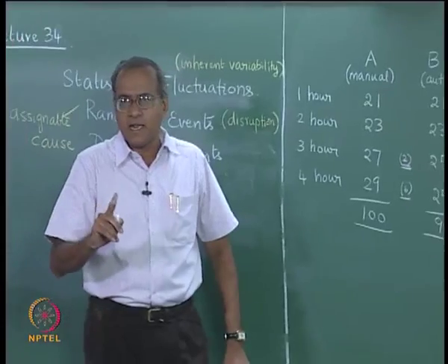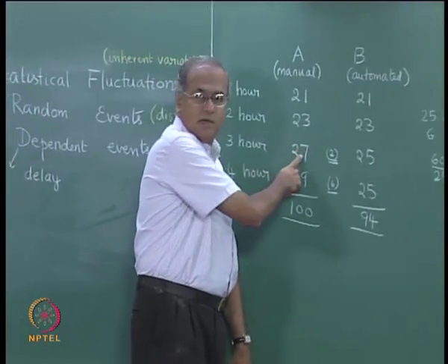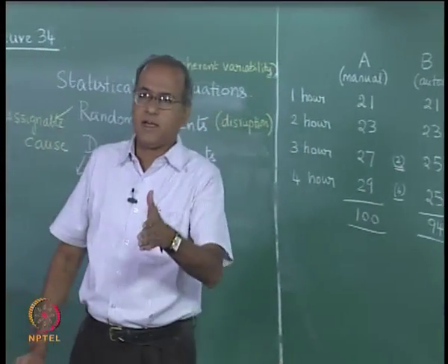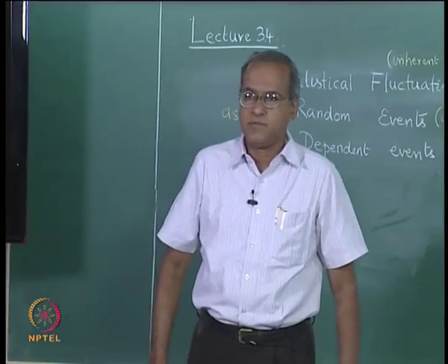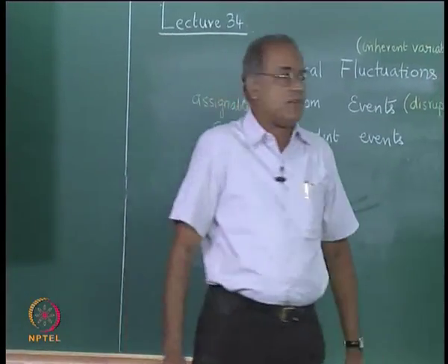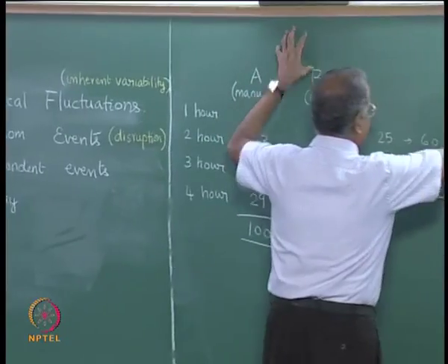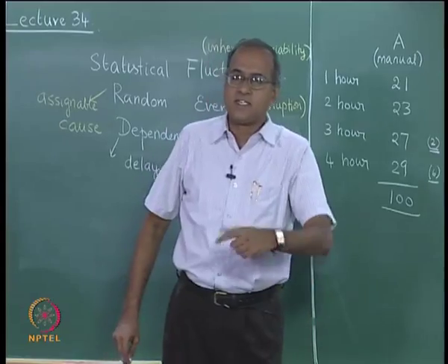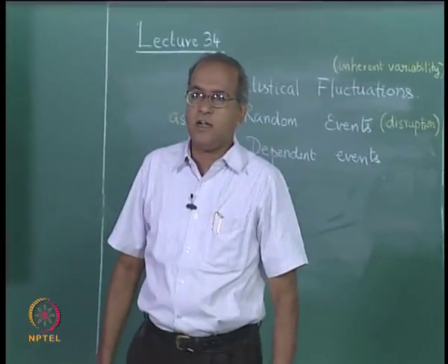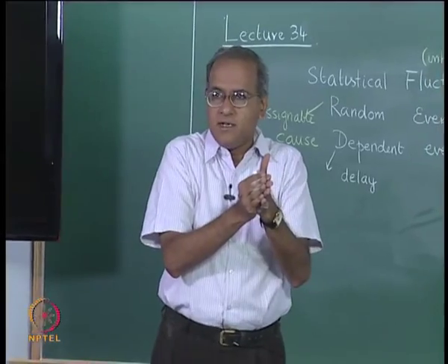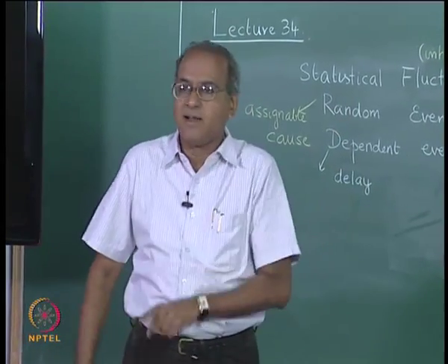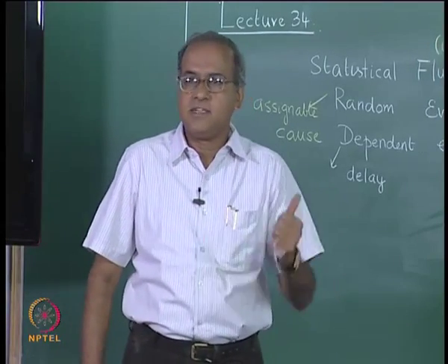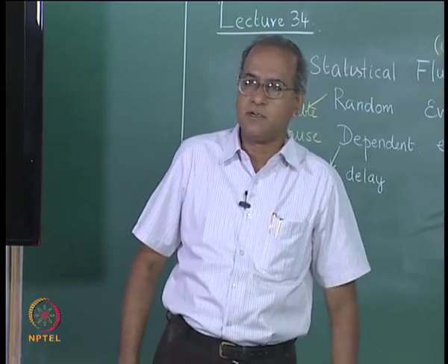The only place where it can be affected a little bit is actually here, because there will be a slight delay for the first piece to come in, which we are ignoring for the purpose of computation. We are not looking at a situation where these two machines are far away and there is a batch transportation every 1 hour. In such a case it will need 5 hours, it will not need 4 hours, because in the first hour the automatic machine is idle, it can start doing only from the second hour. So, it will require 5 hours in such a situation. We are not looking at that situation in this example.